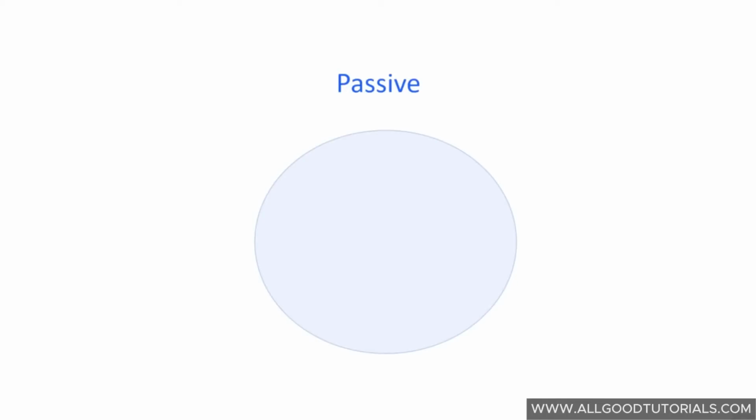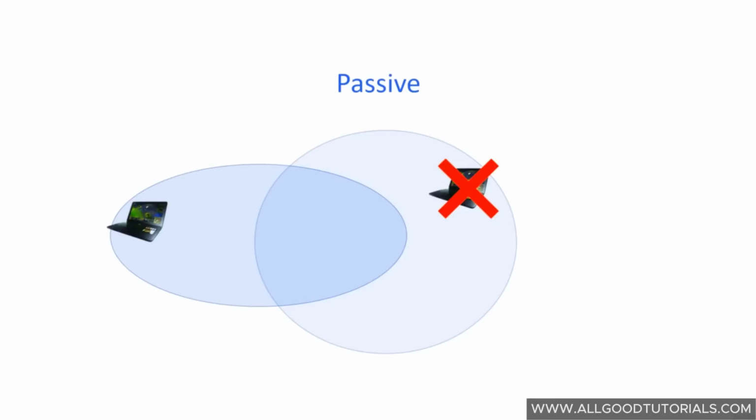Firstly, in Wi-Fi networks, the antennas are passive, i.e. they don't amplify the signal. Let's say, for example, that you're currently using an omnidirectional antenna and it's radiating out, giving you this nice circular pattern. If you change the antennas, you're not changing the amount of energy that's radiated out, you're changing where that energy is radiated to. In this example, you can see that that energy that's radiated out in the circle with an omnidirectional antenna, when I use a directional antenna, it pushes that energy in a specific direction, which means that I can now reach devices that are further away from the wireless router, but it also means that I'm no longer radiating energy in other directions, and therefore there could be devices that I'm now no longer able to communicate with.